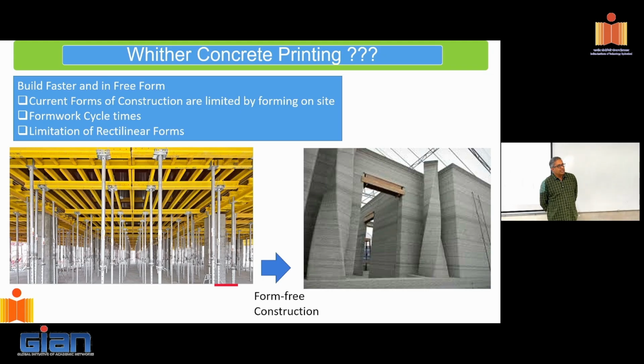Then we resort to pre-stressing. That is the next alternative, and that's where pre-stressing came about, from this whole downward spiral. Now, what is contributing to the downward spiral is all the excess weight that this structure is dragging when you try to meet the demand, because it is rectangular. Now, suppose I was able to take away material where it is not needed, go with even a simple I section, you'll realize that the same break-even point would happen much later. Because now I'm not adding extra weight unnecessarily.